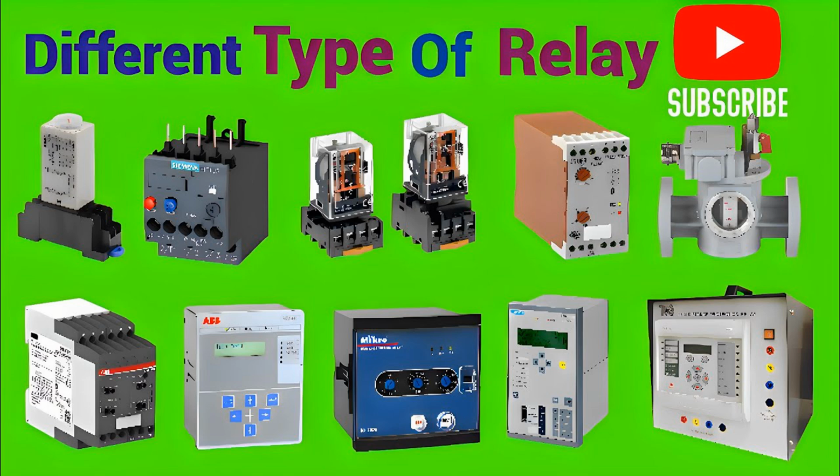Switching action. When the relay is energized or activated, the actuating mechanism causes the movable contacts to move into contact with the stationary contacts, completing an electrical circuit. This is known as the closed or make state of the relay contacts. Conversely, when the relay is de-energized or deactivated, the movable contacts return to their original position, breaking the electrical connection between the contacts. This is known as the open or break state of the relay contacts.